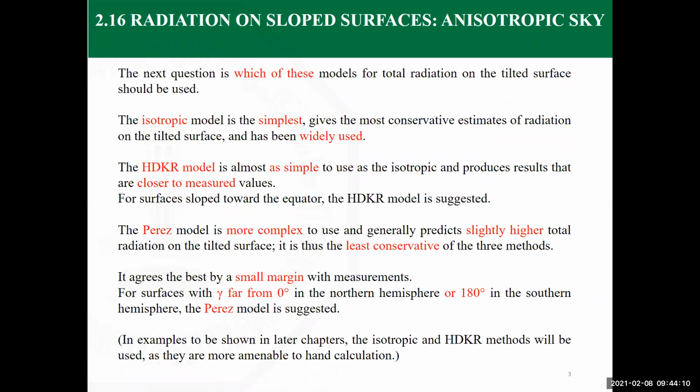And it can be used if you are having surfaces that are sloped toward the equator. The Perez model is more complex. It predicts values slightly higher than the measured values, but it's the least conservative. It's the more accurate of the three models.